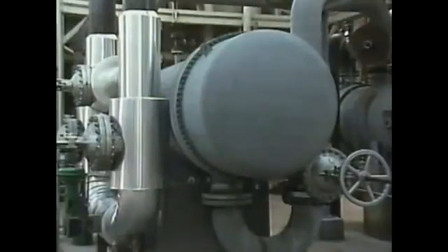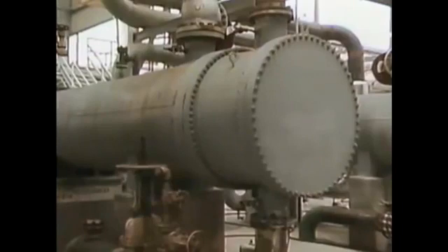Another device that's important for the proper operation of a compressor is a gas cooler. Coolers are used to remove heat that's produced when gases are compressed. A compressor system often has a cooler that is located in the discharge of the compressor and is referred to as an aftercooler. The aftercooler shown here is a shell and tube heat exchanger. In this case, the compressed gas flows through the tubes in the aftercooler, and it is cooled by cooling water that flows around the tubes.